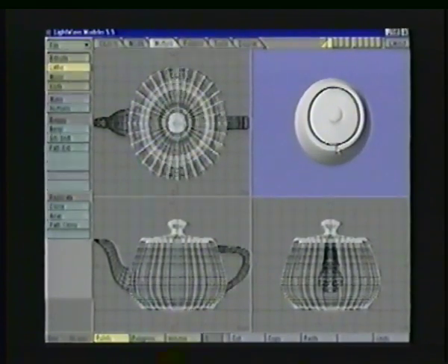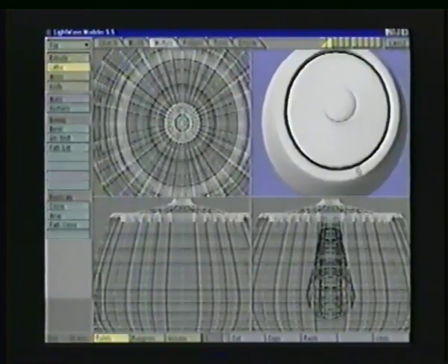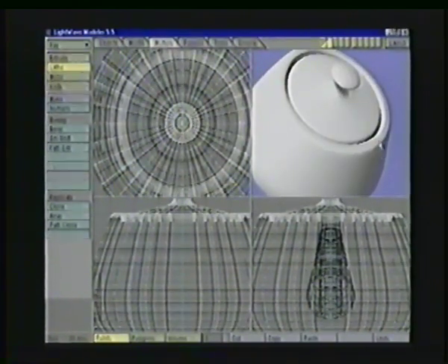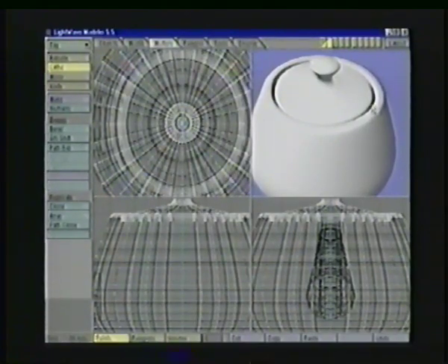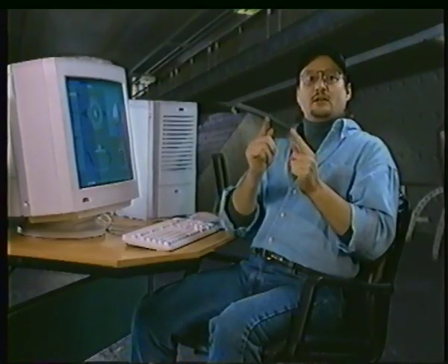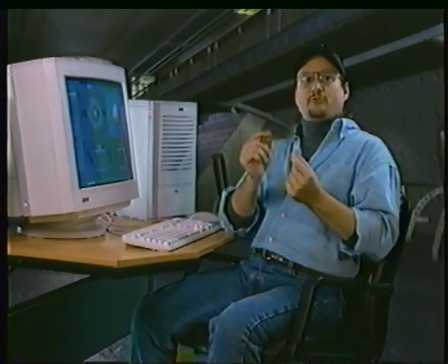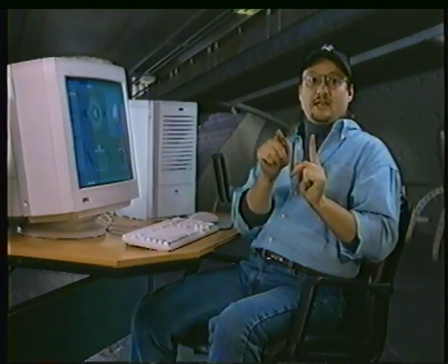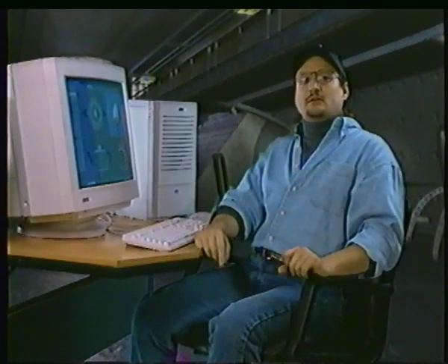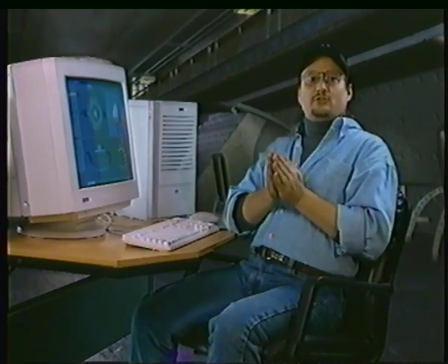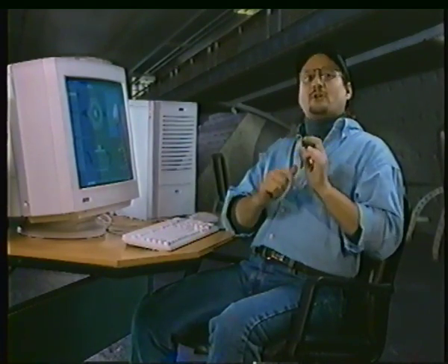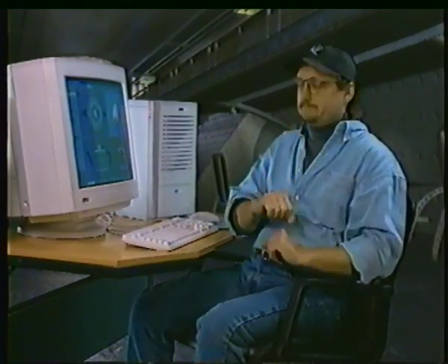And you can see how, if we zoom in, it has a black edge in the middle. Now, by using the start control point and end control point, I was able to get a much tighter curve than they were here. By adding a control point to the start of a curve or the end of a curve, it allows us to maintain the continuity of the curve across the lathe, or if we were mirroring. In a minute, when we work on the spout, we're going to be mirroring 2 sets of curves, and we're going to be using a similar command called smooth. But first, let's work on the handle.